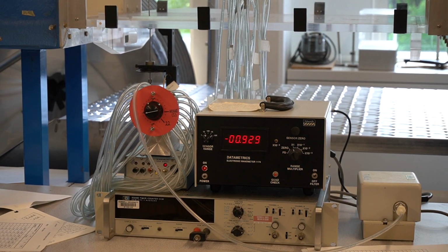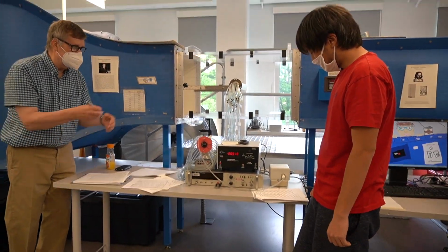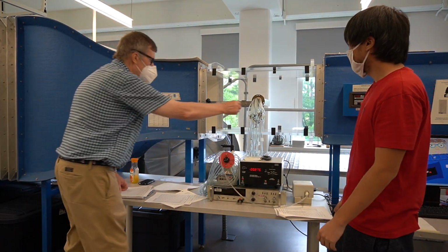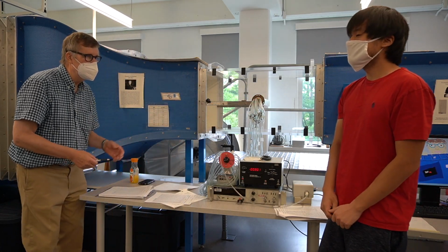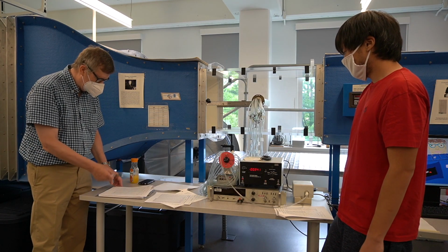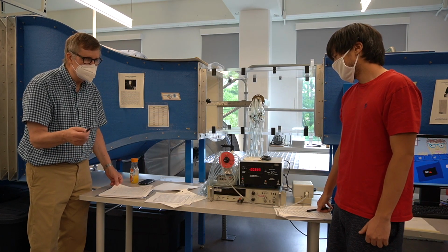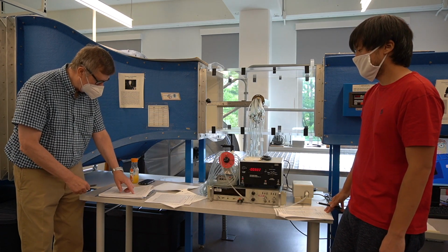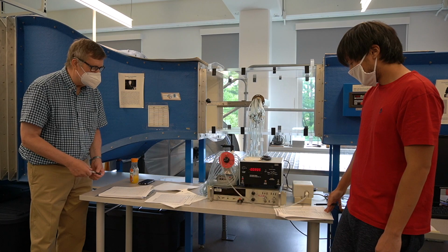Okay, and then I'm just going to say, for the purpose right now, that you go all the way to the very rear, at the middle of the rear of the body, and the pressure is remarkably constant as you traverse from the top to the bottom of this back surface of the cylinder. So when you add up all the P minus PS's, the pressures at different pressure points P, you multiply them by the weighting function, and you add everything up at the end. We don't know what you get.